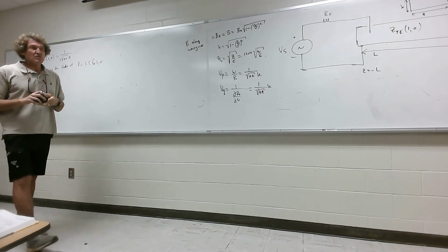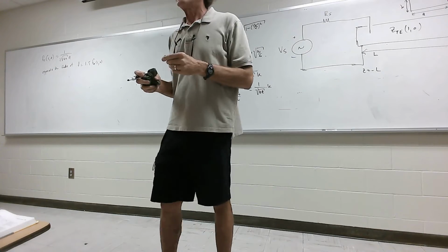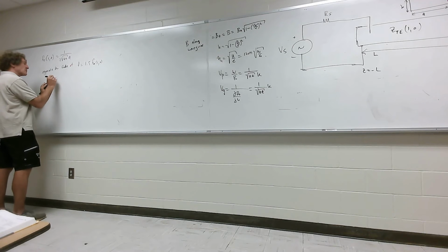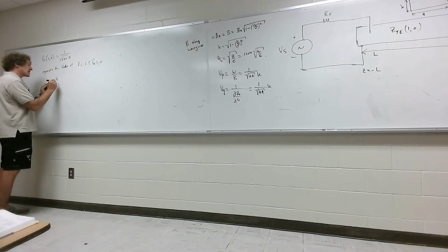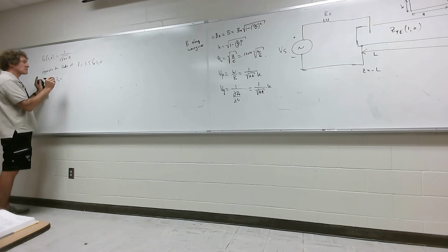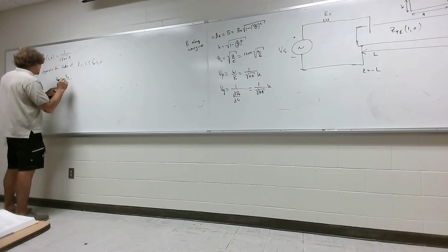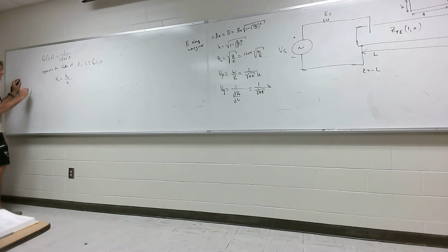Now, what is this really going to look like, this mess right here? It's going to look like a transmission line problem. But here's the difference. You remember, for transmission lines, you had a characteristic impedance Z naught. Now your characteristic impedance Z naught will be equal to really eta over K, and K, of course, is equal to the square root of 1 minus (FC over F) squared. Now, for our case, I've told you that we're operating at 1.5 FC.